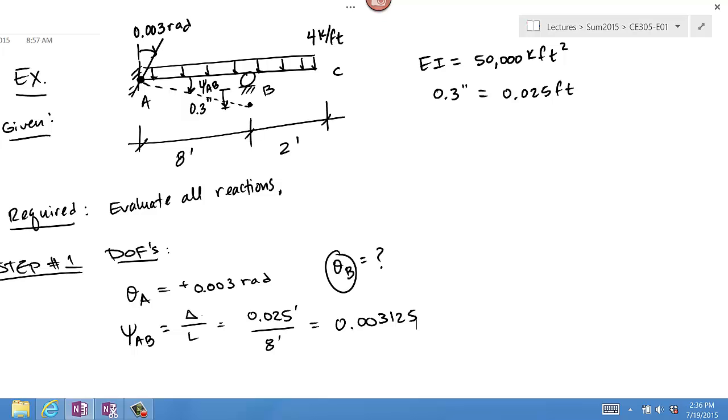Well, this is a cantilever span, so it's kind of the third type of span that you might see. And so for cantilevering spans, you basically can solve terms using equilibrium. You can solve for example, for the moment BC using equilibrium. So you don't need to define another slope deflection equation for span BC.